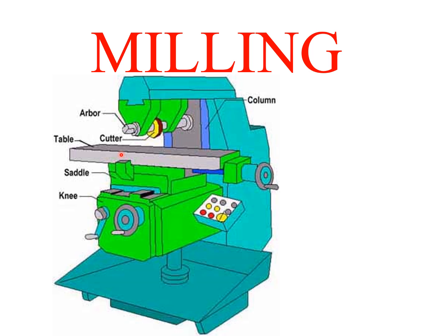The milling process removes material by performing many separate small cuts. This is accomplished by using a cutter with many teeth, spinning the cutter at high speed, or advancing the material through the cutter slowly. Most often it is some combination of these three approaches. The speeds and feeds used are varied to suit a combination of variables.